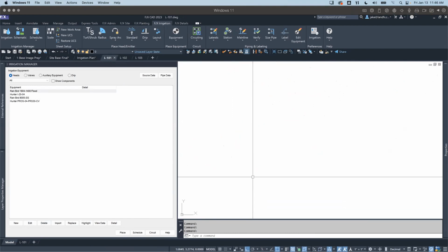What that allows is a lot more flexibility with line type issues, especially if we're using multiple scales on different parts of the drawing. There's no way in one file to accomplish multiple scales of the same line type in a single drawing. You're always sitting there toggling.